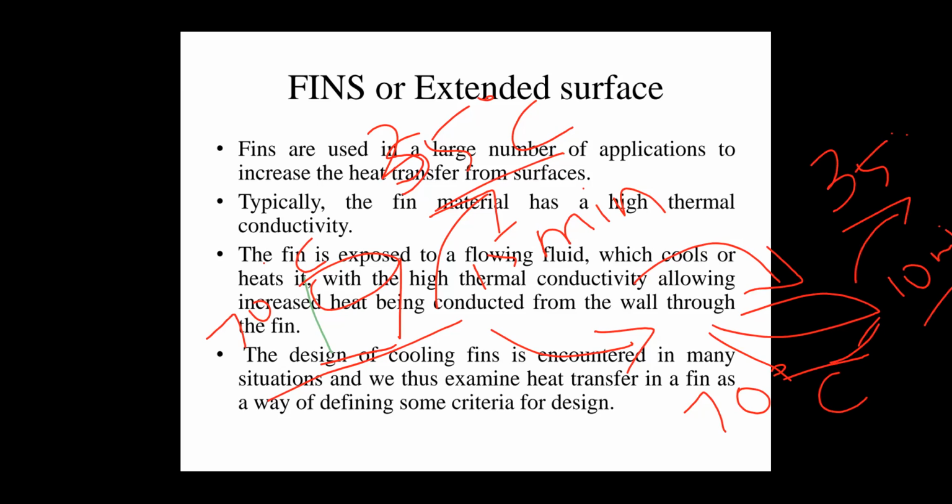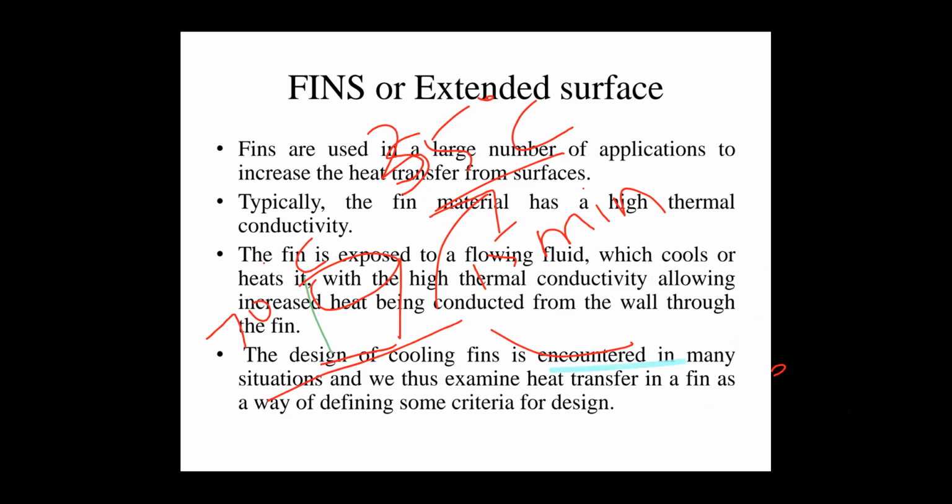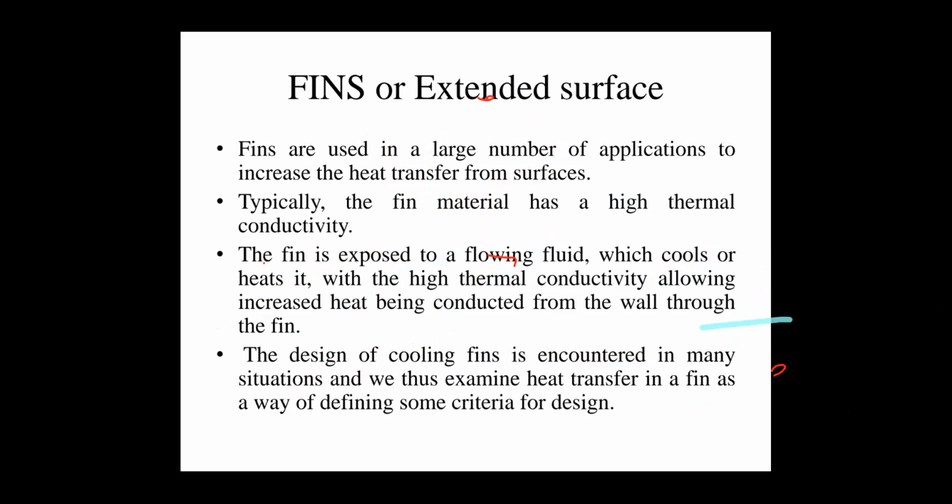The same concept: Newton's law of cooling says that if the surface area increases, the heat transfer is also increased. That is why heat dissipation is increased. That is the reason the extended surface works on the principle of Newton's law of cooling. The formula for Newton's law of cooling is Q = h × A × (Ts − T∞).